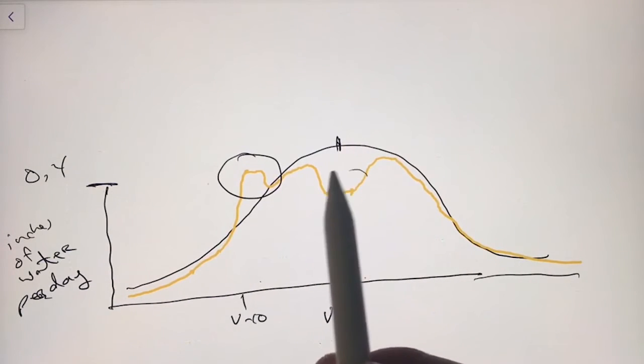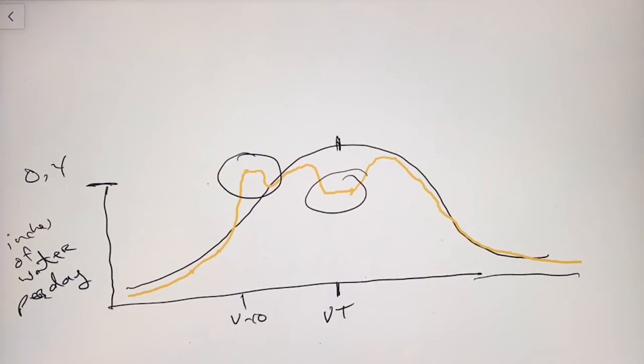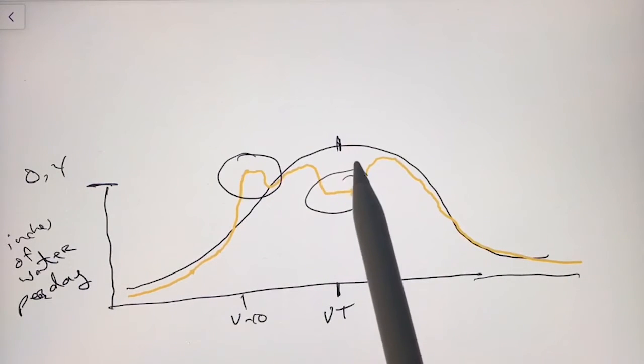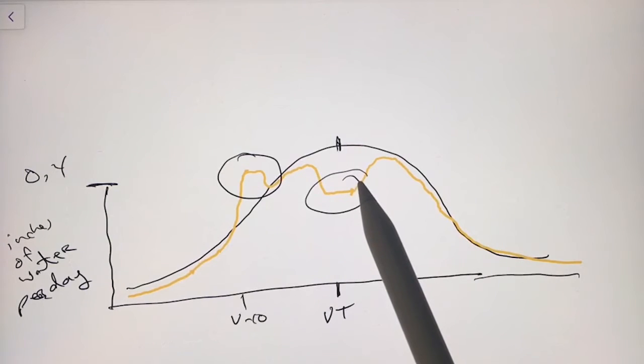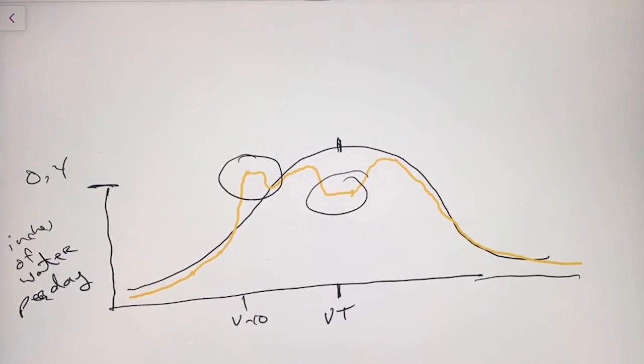Here we are actually over irrigating if we were looking at the average crop water use by the plant. We're actually putting more water out there in the system than is needed. So we're spending more money than is needed on that plant because, again, we've got lower temperatures out there with a cloudy day and the corn plant is not using as much water. So again, this is an important concept for farmers to keep in mind as they look at irrigation scheduling.